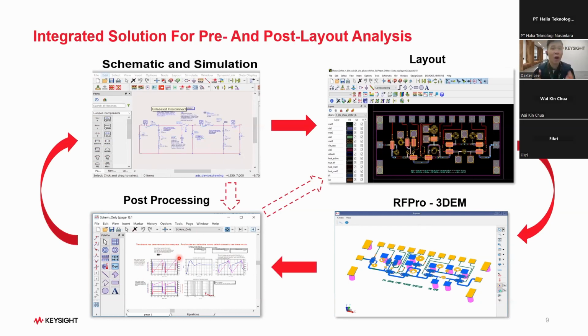One good thing that we often hear from our users about our data display, which you are seeing right here, is that you are able to do post-processing. So whatever data you have from the S parameter simulation results or the harmonic balance simulation results, you are able to do post-processing through some of our equation-based features that we have in data display for you to manipulate and do post-processing. Okay.